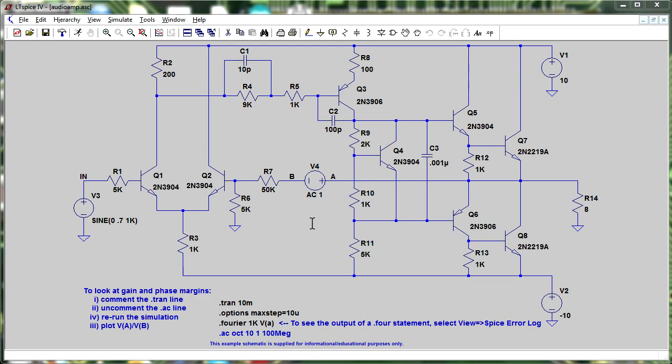You really have to tweak this and tweak that. Now, the good thing about LTSPICE is that as you get it out of the package, it has actually been tweaked and optimized for pretty good convergence for board level circuits, and in the case of LTSPICE, more specifically designed for power switching regulator simulation and stuff like that. But as a general purpose simulator, it does work really well.